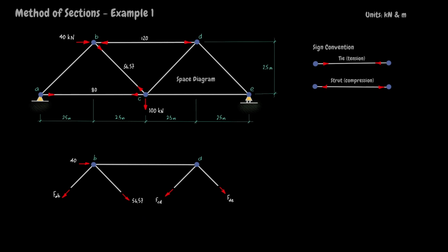Of course, we could apply them, and if you like solving simultaneous equations, it's the way to go. But Dr. Jim prefers to sidestep simultaneous equations when possible. So, how to proceed? Pause the playback and think about it. We see that taking moments about D will yield FAB. The downside of this is we need to know the lever arms of FAB and FBC about D.